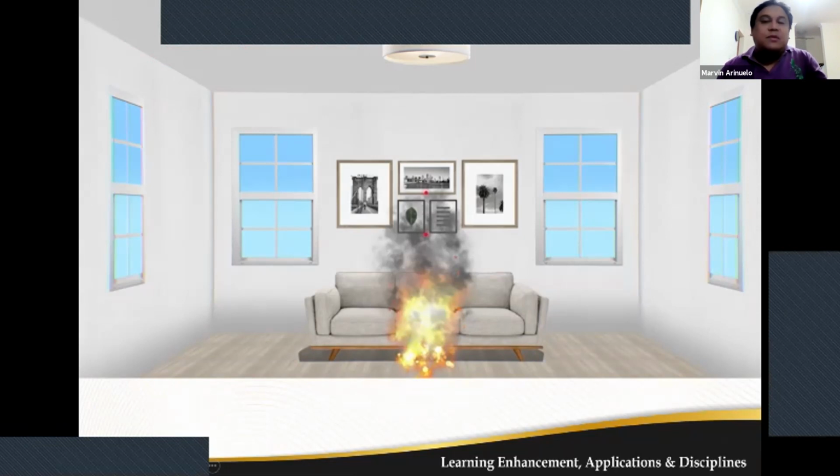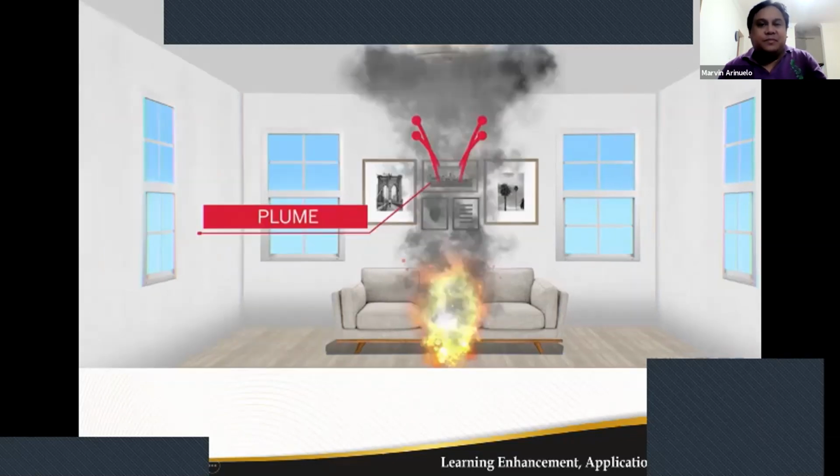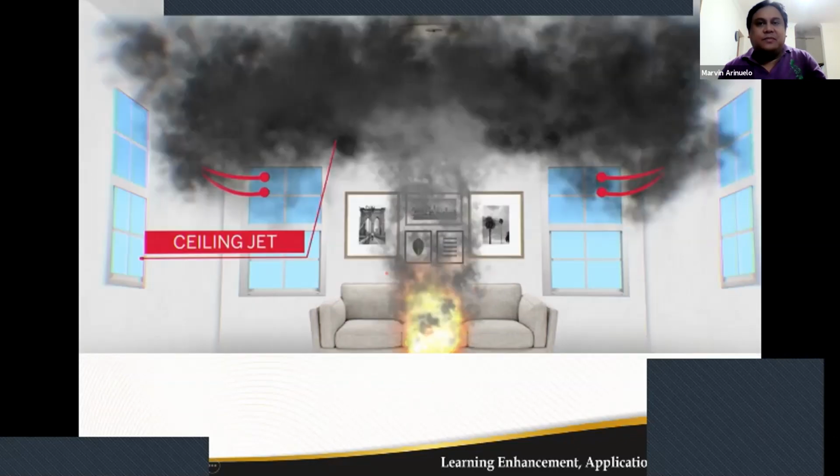In the physics and chemistry of fire, you will learn that the fire plume and buoyant gas rise up in the open environment. Now, let us imagine you are inside a building. So again, this is just to recap. Rising hot gas proceeds to the ceiling, which then turns horizontal. And this is called a ceiling jet, turning from the vertical to the horizontal direction.